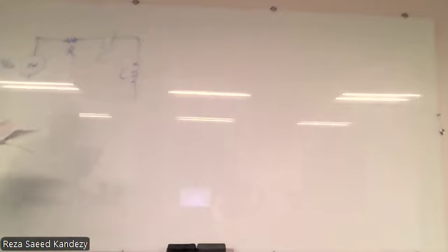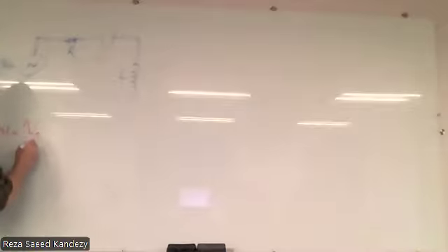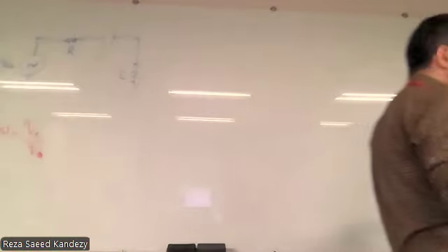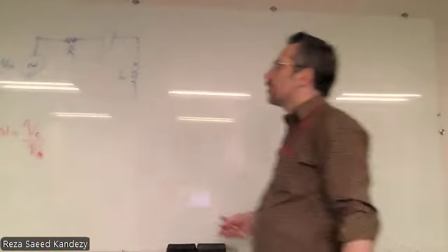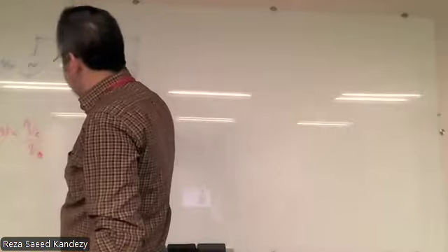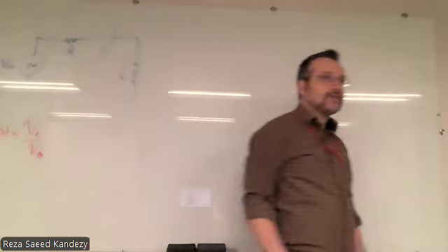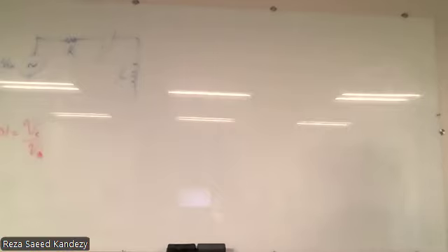And what we want as H of s is the voltage across the capacitor over the input voltage. Now, we have several ways to deal with that. In the frequency domain, we learned that we can simply replace the components with their impedance.